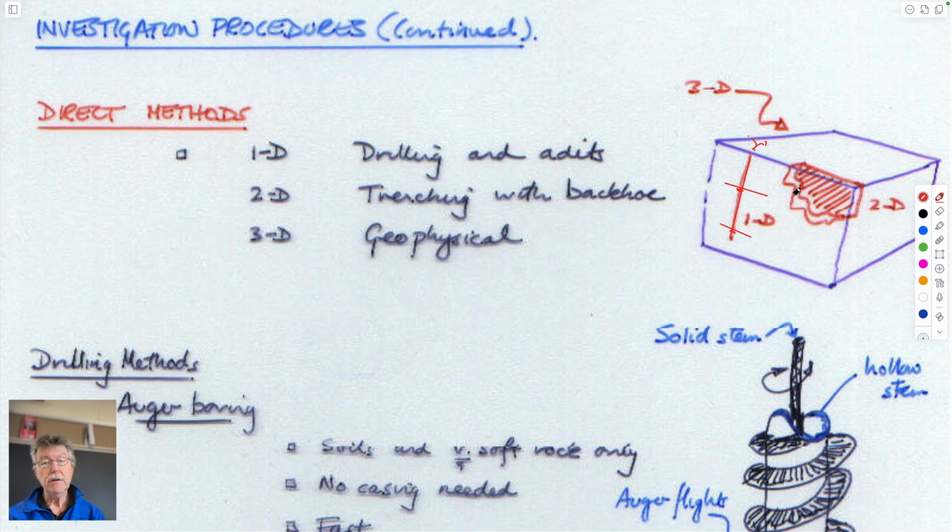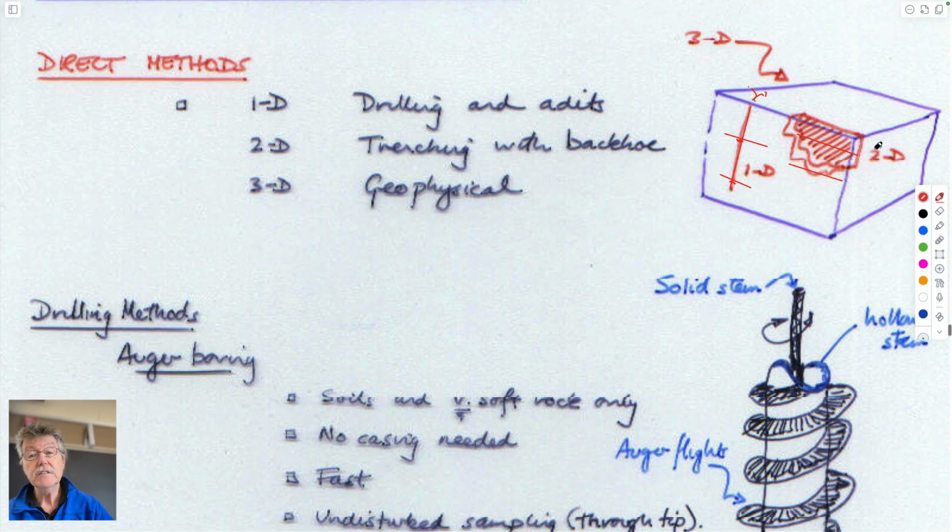If you drill a trench with a backhoe and get into it, at risking your life if it collapses, of course, then you also get some idea of the stratigraphy, but at relatively shallow depths, talking 6 feet, I would think, for this. And probably you shouldn't do that because of OSHA type rules, because the trench can collapse on you. And if you want to see what a 3D picture is, of course, if you excavate the whole site, you don't have a site to worry about. So perhaps problem solved, but you can rarely afford to do that.